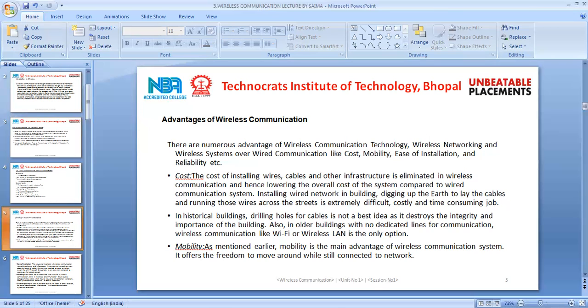Furthermore, there is an interfering transmitter at a distance capital D from the desired base station, which operates at the same frequency and with the same transmit power. How large does D have to be in order to guarantee satisfactory transmission quality 90% of the time, assuming that the mobile station is at the cell boundary? Now, this is the worst case which we can consider.